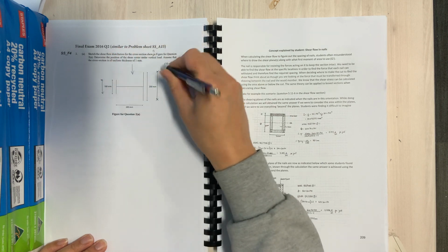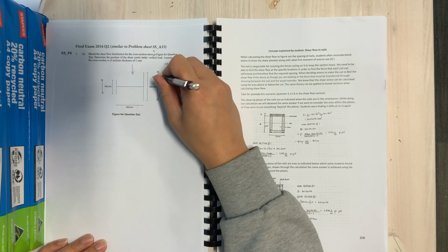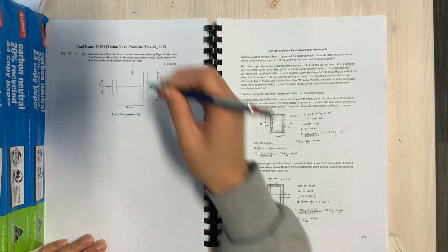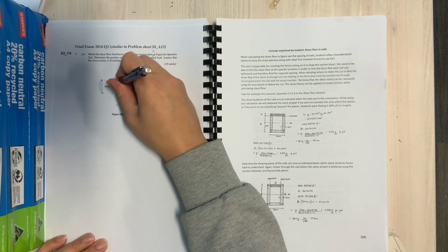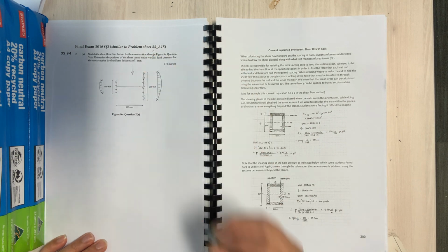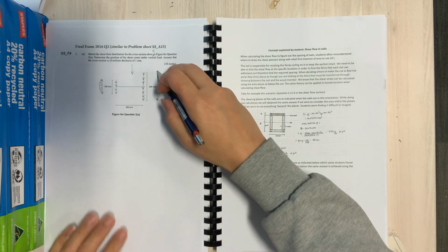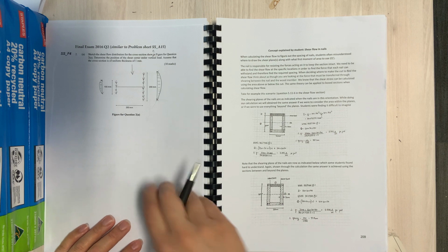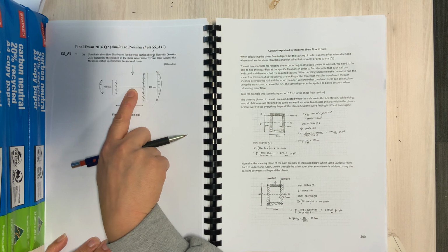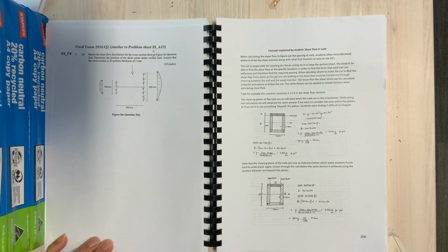So we know that the vertical members are going to be taking the vertical stress. So you would expect a parabolic distribution there, and you would expect a parabolic distribution there. And we might maybe say that the shear flow would be going down like there in those two members there. Okay. So once we've got the shear flow, which would be the area under the parabolas, then to work out the position of E, you can find E just by taking moments. So obviously E must be nearer to that side than that side in order for the two to balance out.